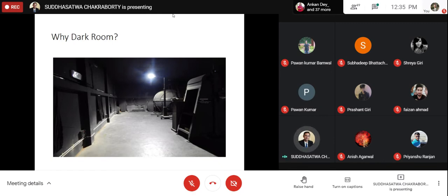If it comes there and my measurement is taking care of the reflected component too, then where will be the problem? The problem is that while I'm going to characterize my light source, maybe my luminaire, this light with the reflector or the fixtures assembly, so I'm going to use in any situation. So I don't know what the situation I'm going to take. So my dark room should only measure the direct components, because the indirect component will vary with the different situation.